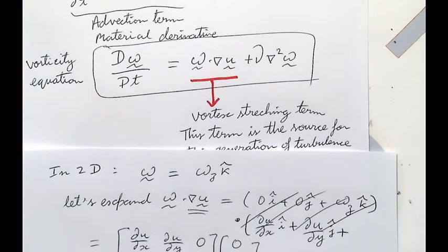It will not get killed off, except by the diffusion term, but not because of this mechanism of cascading energy. Okay. So strictly speaking, in a physical sense, it's not turbulent, right? It will still be unsteady and disturbed flow, but there's no mechanism of energy transfer. Does that make sense?